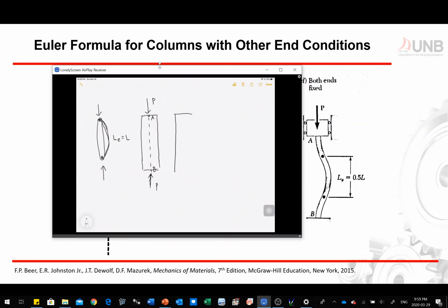So wherein our load is not exactly at the center of our column. Let's say we have P right here, and let's call this one E. That's the distance from this point up to the center of the column. And then we have another P right here. So how can we solve such a problem? It's called eccentric loading, and the secant formula is the topic in your book.